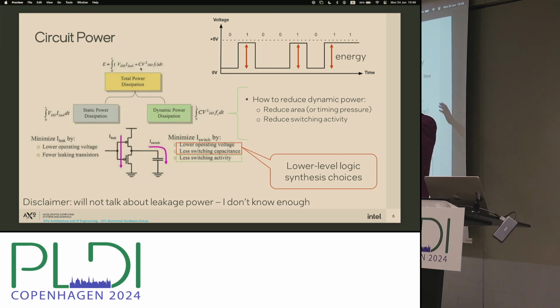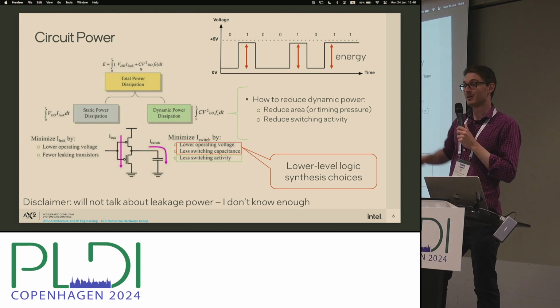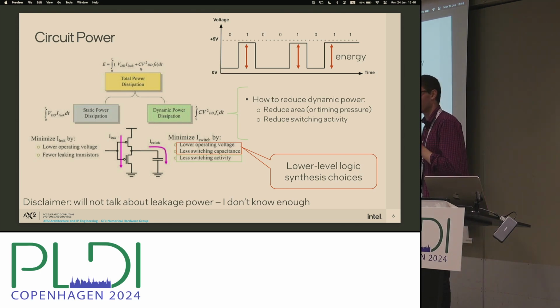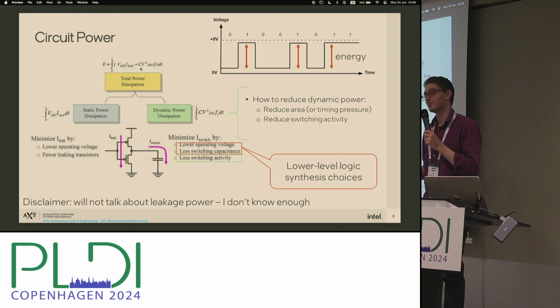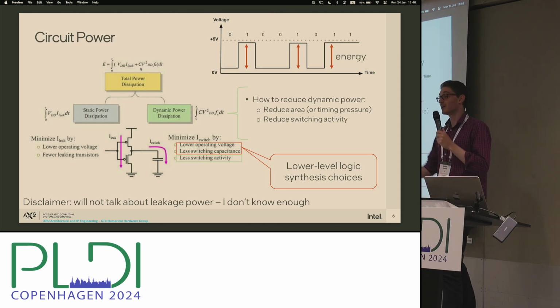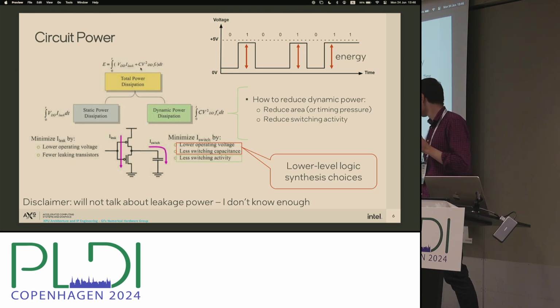And so you can either reduce the number of gates, or reduce the number of signals you've got passing around, so that means you're doing less up and down overall. This is reducing the switching activity, meaning you're doing less up and downing, and so you're consuming less energy. But obviously you really want to be doing this and producing the same computation. I can produce 0 out of my circuit and use 0 energy at all, and that would be very efficient.